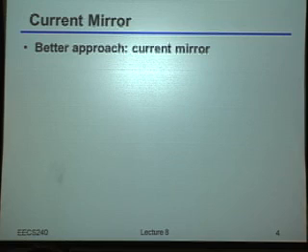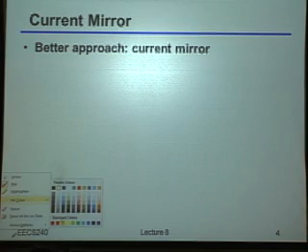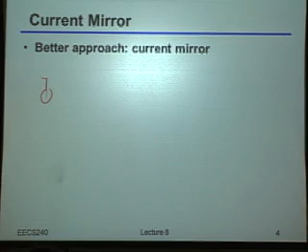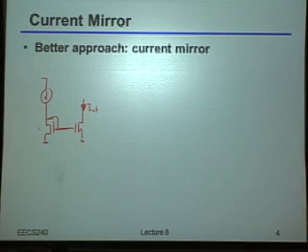Now, I'll just quickly draw it, and then hopefully someone will jump up and sort of be upset with me. So the classic current mirror, of course, is you take some reference current, you feed that into a diode-connected device, and then you feed that diode-connected gate voltage to another device to create your output current. Okay, so for example, and typically you'll do a ratio so that you can scale the current up or down from that reference current.